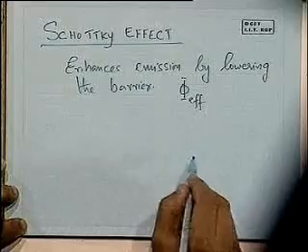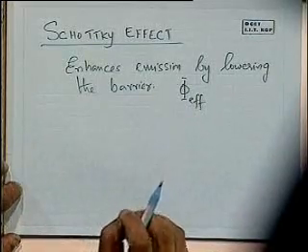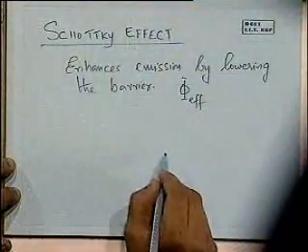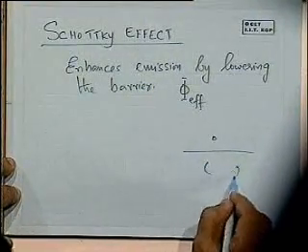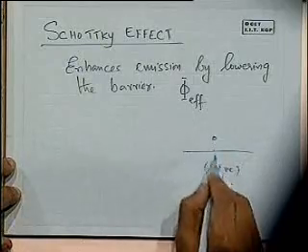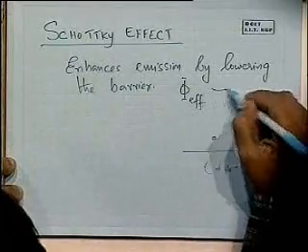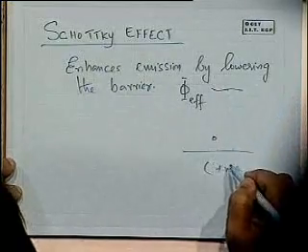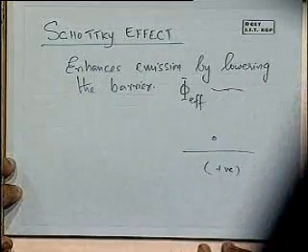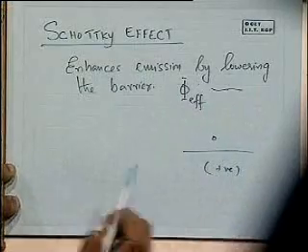Consider an electron just outside the surface of the metal, and we are going to look at what are the forces that are acting, what are the barriers that it sees. When the electron has gone out of the metal, there is what is called an image force, as if there is an apparently positively charged region that is pulling back on it. And then in addition to that, we have the applied bias applied to the anode. And then you have the thermal excitation that is also there for the electron to go out. So these are the different forces that are acting on this electron.